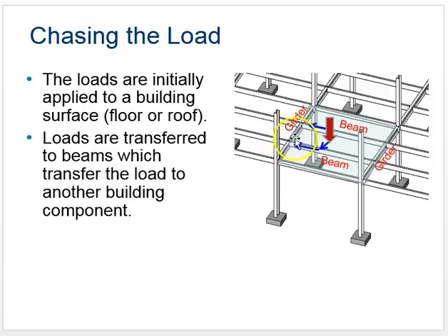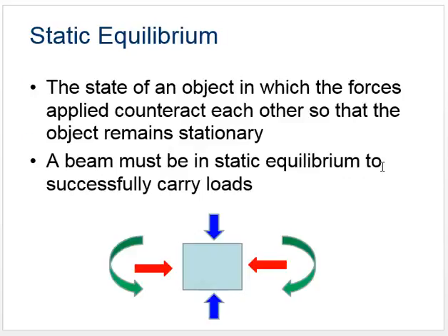We've seen this picture before, our beams and our girders. On our beams, the tributary weight is putting uniform load on our beams here. And then we also have uniform load from the tributary weight on our girders, as well as these point loads coming from the beams themselves. So we'll see both of those combinations when we do example problems.